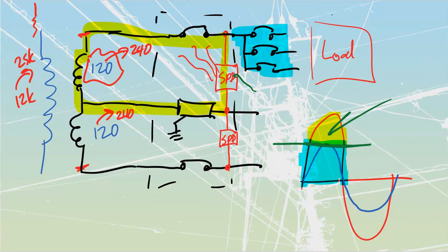Possible sources are usually from outside, and they're going to be a transient. They're not going to be something that's considered to be always on the system. If I've got a voltage that is always on the system, I'm going to have to adjust my transformation ratio. You use a tapped transformer or change transformers altogether. This is for momentary stuff. Lightning strikes are a big one. Lightning strikes are going to raise your whole grid.